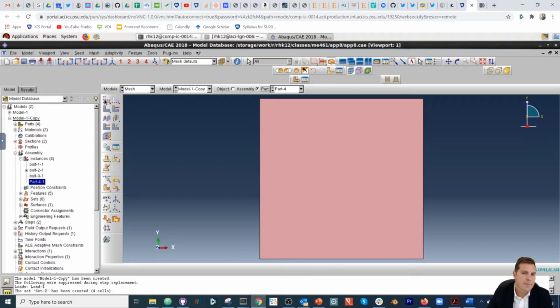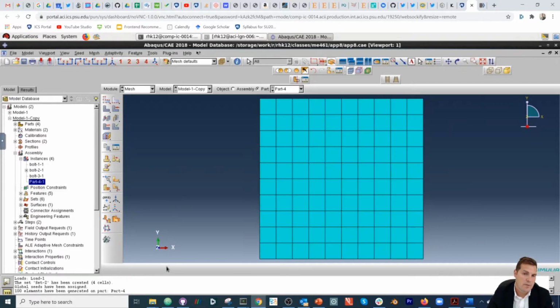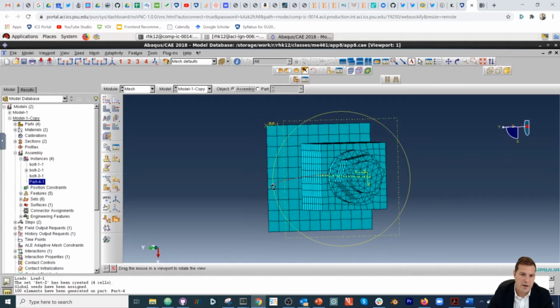It's interesting. So I'll just go right ahead and mesh the part and take the defaults for the seeds because I don't really care about this. The only thing I do need is these elements to work for contact. So that's one thing that you have to be aware of if you do this for a different problem. In this case, I know that it works. So here is our sort of entire mesh discretization.